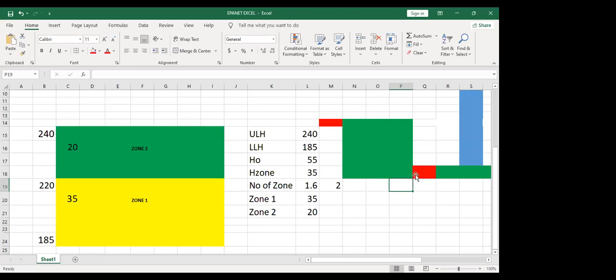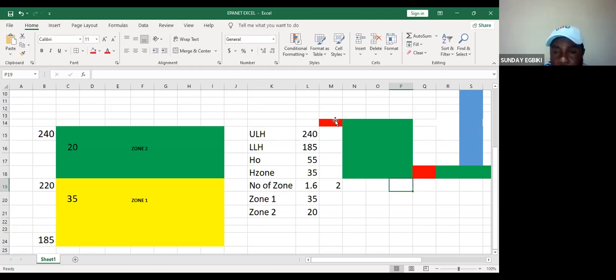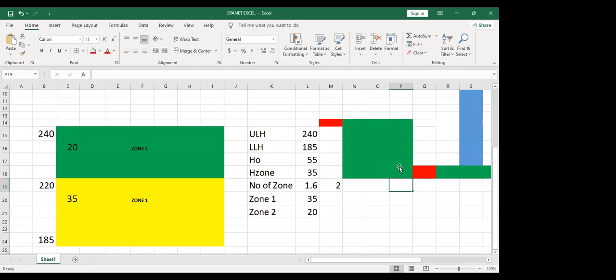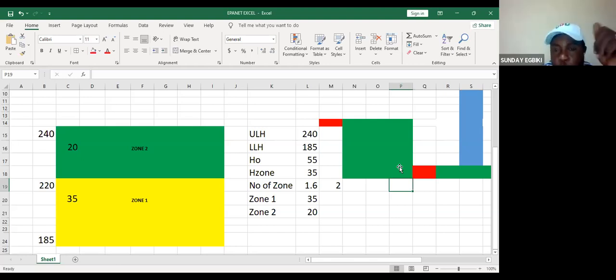Just consider the tank, then the upper one is this. But in a deep tank situation, we have what we call a buffer that will not allow the tank to be filled to the brim. In EPANET, the freeboard. On Saturday, when you will be using EPANET to size your tank, you will see EPANET will require this value from you, from here to this place.